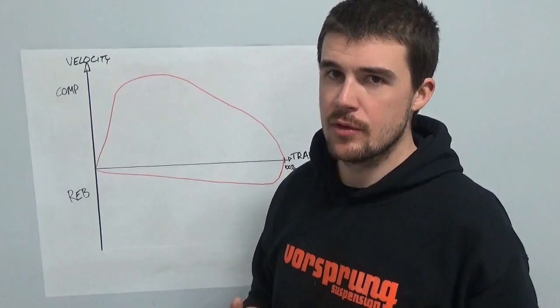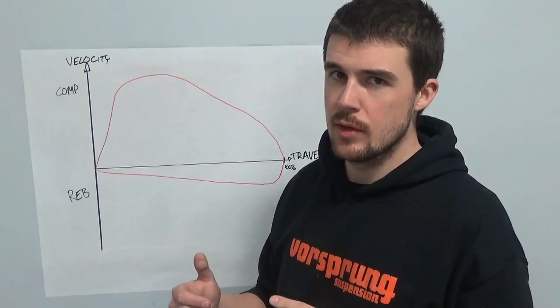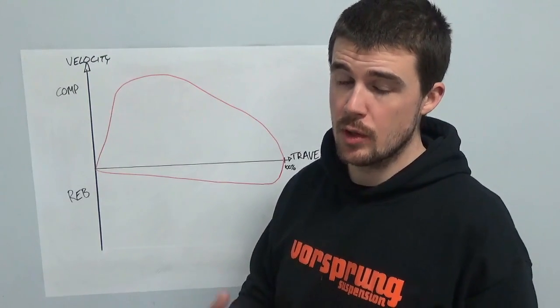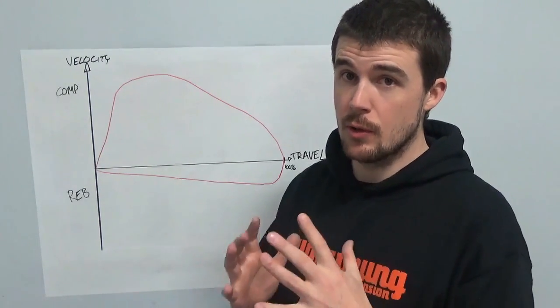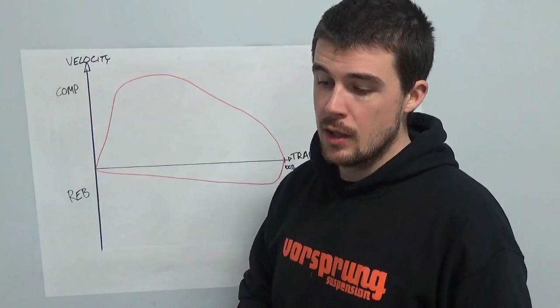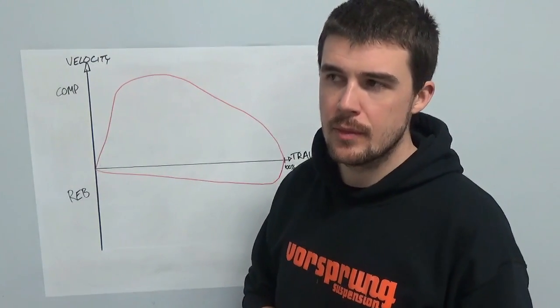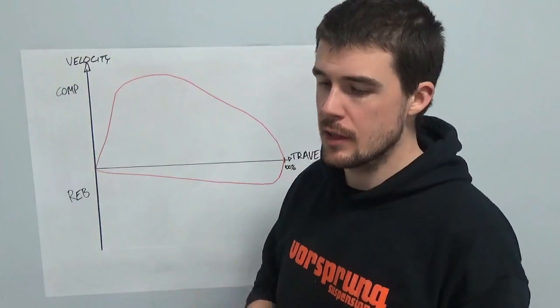None of these dampers are amplitude sensitive or position sensitive like the boost valve systems were, which relied on IFP pressure holding the valve closed. And so those claims are essentially, if nothing else, semantically incorrect.